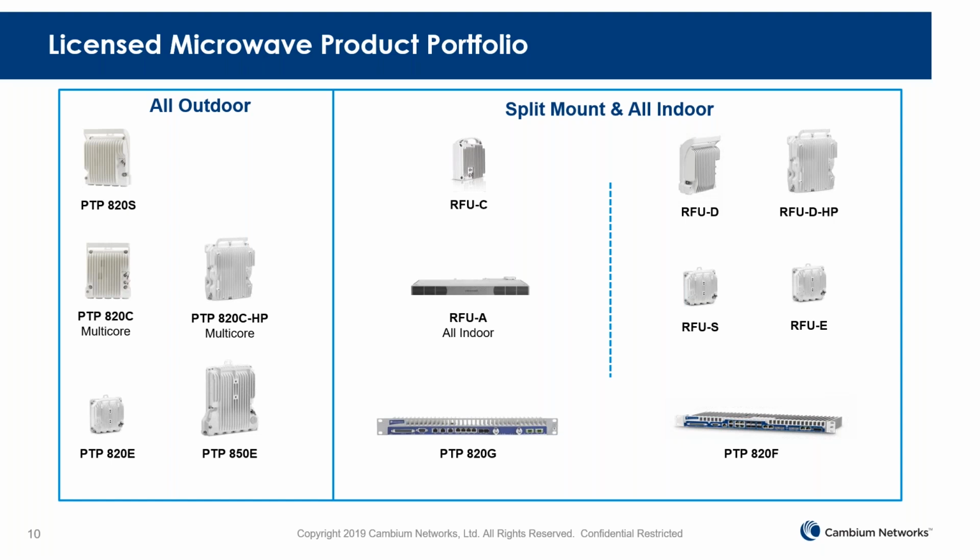You can also use some natural environment, like if you're on the rooftop, you may use the rooftop to give you certain blocking for the signals you don't want to receive, or you purposely install the antenna or radio using something like a chimney to block certain interference from certain directions. Because keep in mind, interference is very directional. You can leverage those things to give you better performance. So that's just something we also recommend when you do the sub 6 point installation.